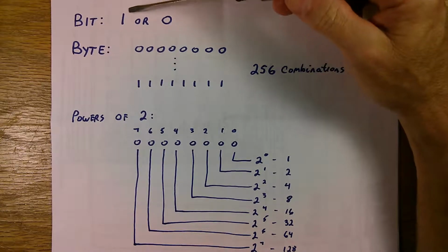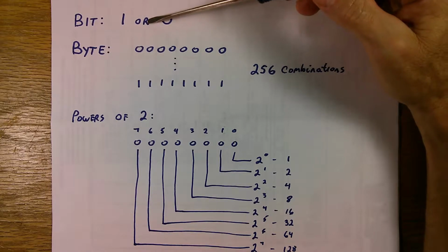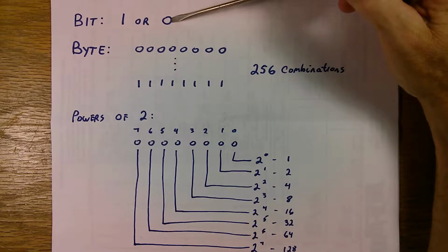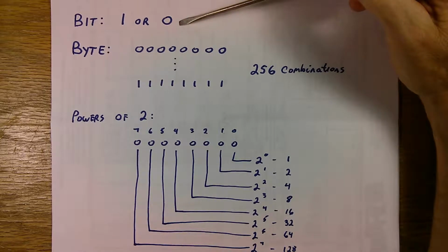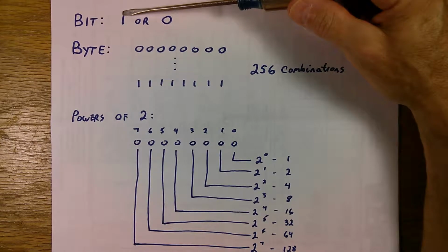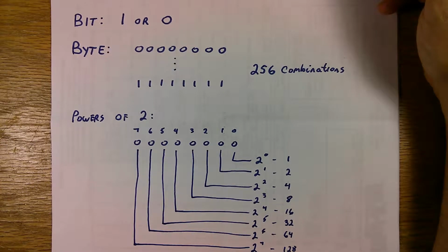And you'll notice that there's a gap between 3 and 1.5 volts where there's no logic level defined. So you must get the pin below 1.5 volts to get it to read a 0, or get it higher than 3 volts to get it to read a 1, or whatever it might be. That voltage level will be different if you're running the microcontroller on 3.3 volts. Or other microcontrollers that operate off of different voltages. Some microcontrollers run at 1.8 volts or 2.7 volts.